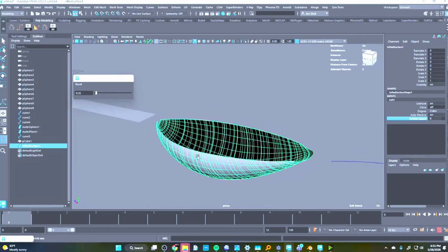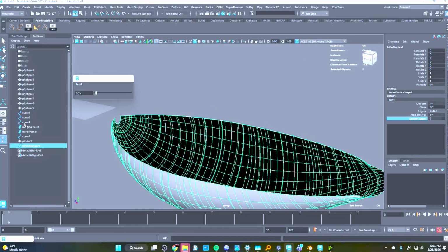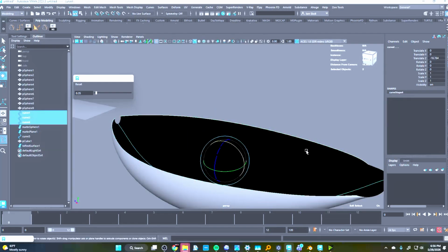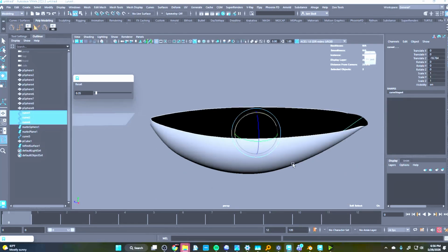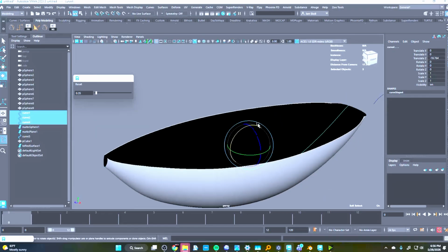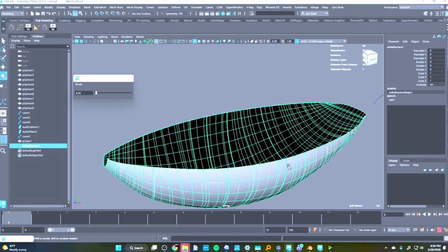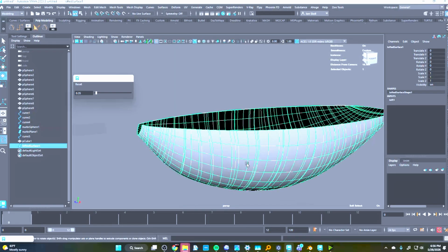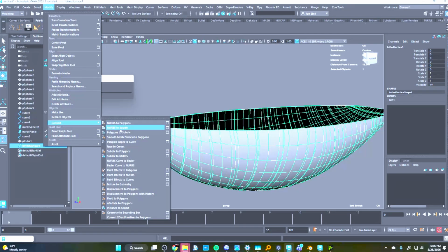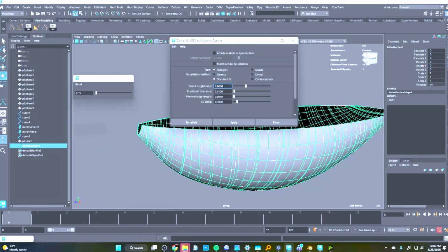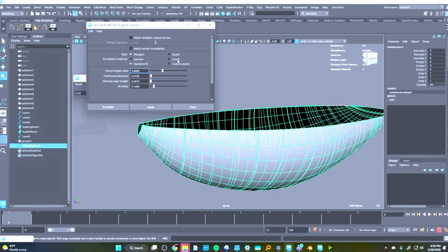Now, in the computer world with NURBS, let's get back to NURBS here. Okay, so we had these three curves. Well, we can't do much with curves. We can animate them, we can kind of use them, but they are not as friendly to work with after this initial stage. So what you want to do is turn this into a polygon mesh. We have tools that convert from NURBS to a polygon. So let's see, NURBS to polygon. You can get this little checkbox here. And there's a whole bunch of ways to do it.